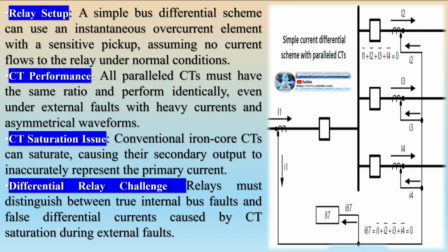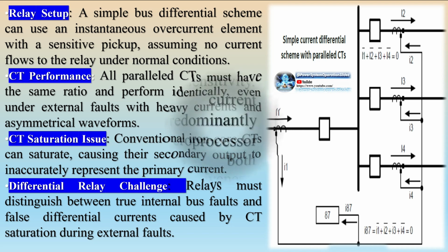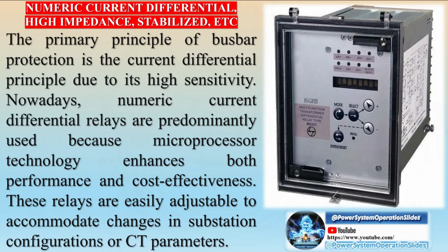Circuit breaker failure protection (BFP) is a local backup protection function that operates selectively in the event that a circuit breaker fails to interrupt fault current despite receiving a tripping impulse from its protection. The goal of BFP is to minimize the number of bays tripped, ensuring that only the necessary sections are affected.